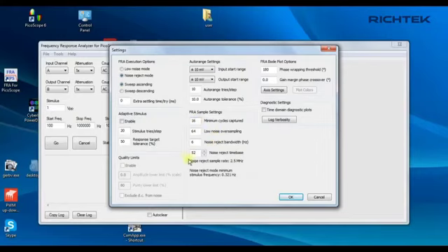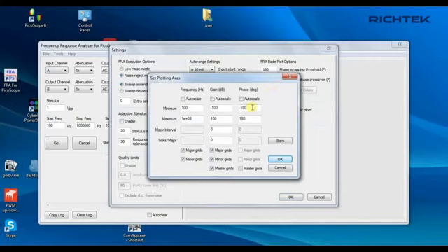The noise reject time base must be set low enough to get a sample rate that is at least double the converter switching frequency. The Axis Setting menu lets you set the plot scale and grid. I recommend using symmetrical scales for gain and phase, so the 0 dB and 0 degrees line up.